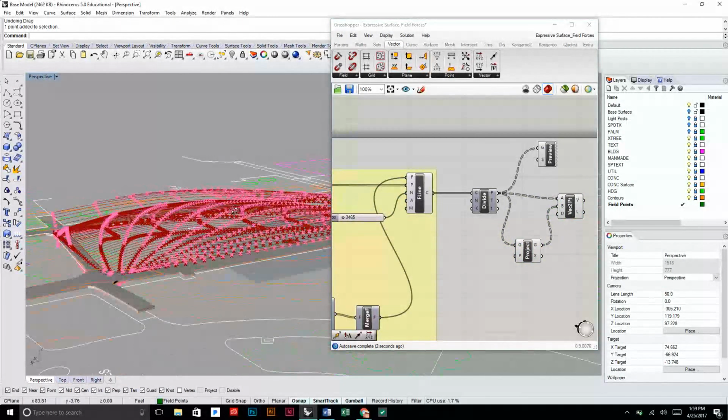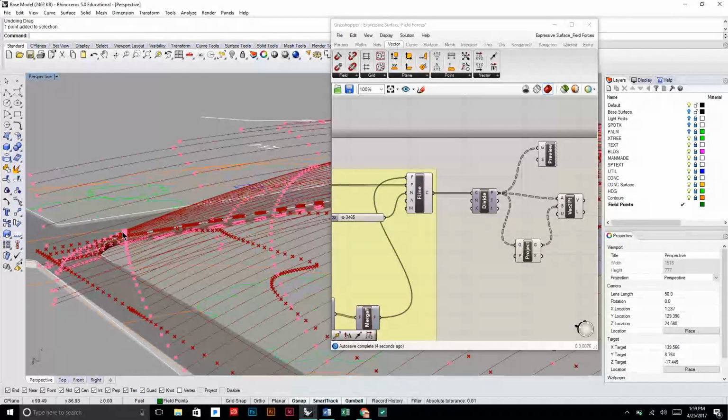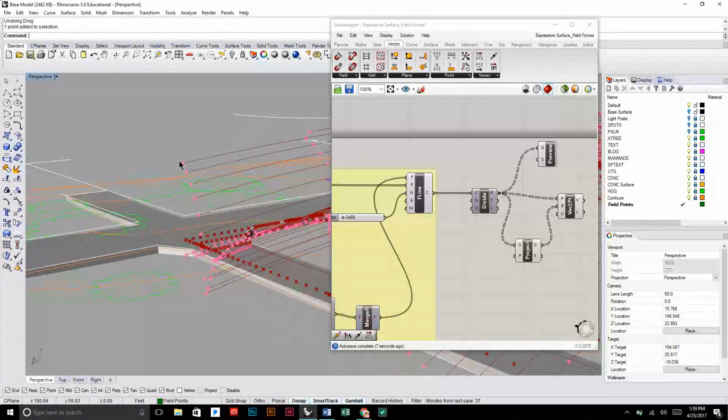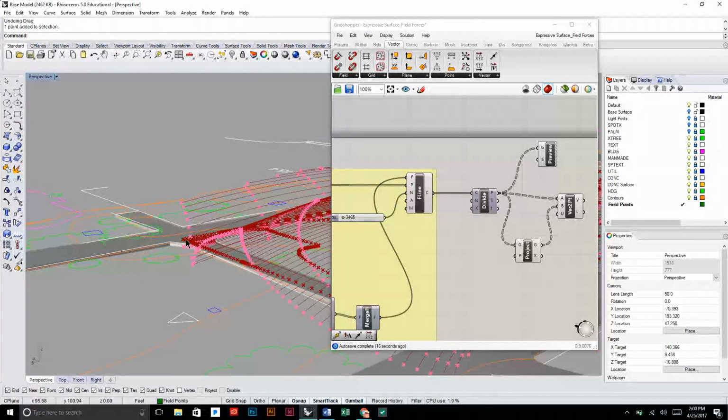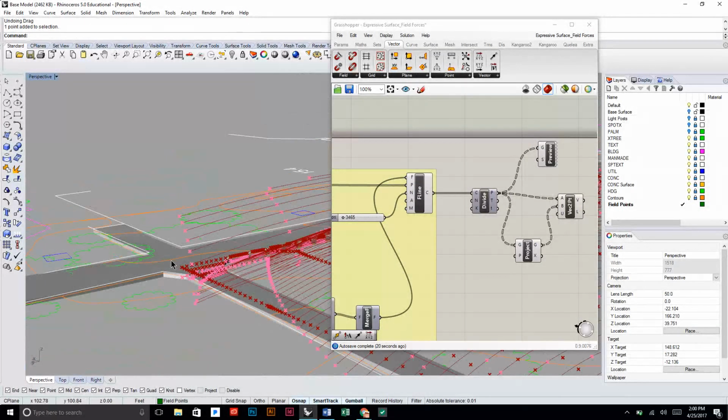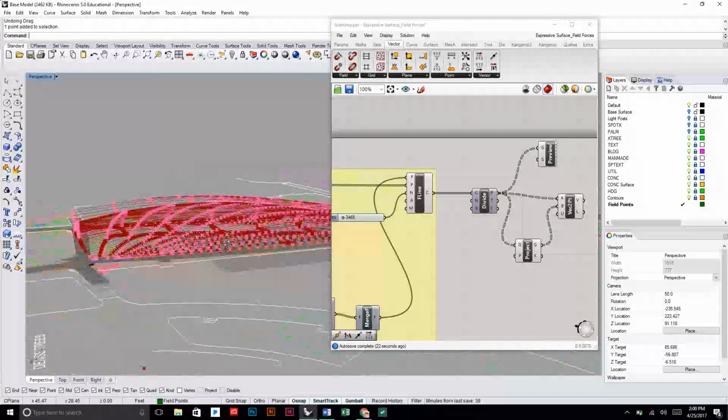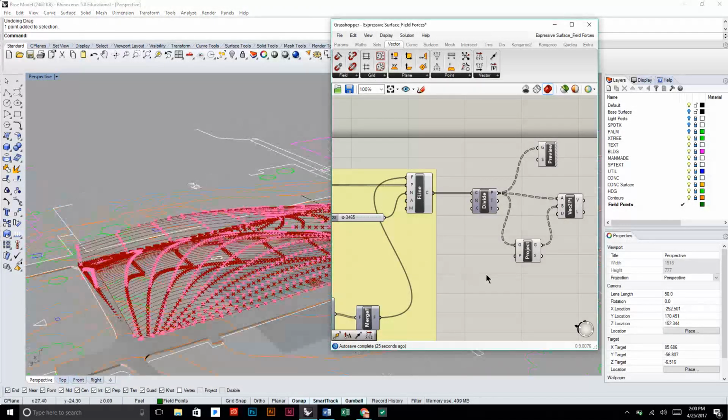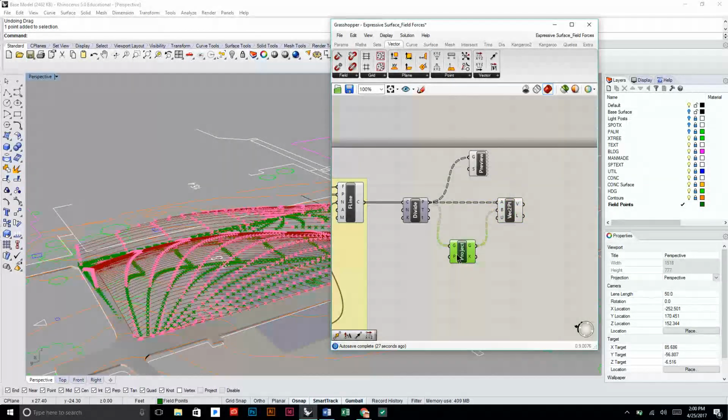So this is basically just telling us what that movement is from, for example, this point to that one that's been projected down. And what we're basically going to do is say, okay, for these ones that are really close, return it to this projected, but then as it gets further away, taper back to the original. So in order to do that, we need to use a graph mapper to create that kind of fluid transition.